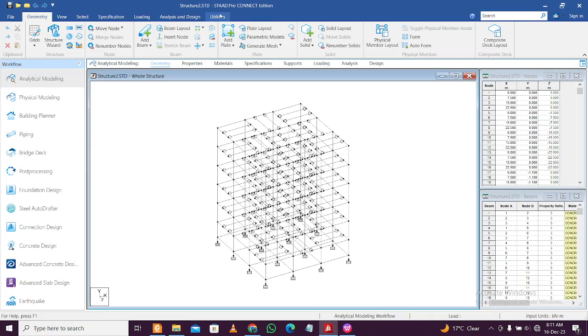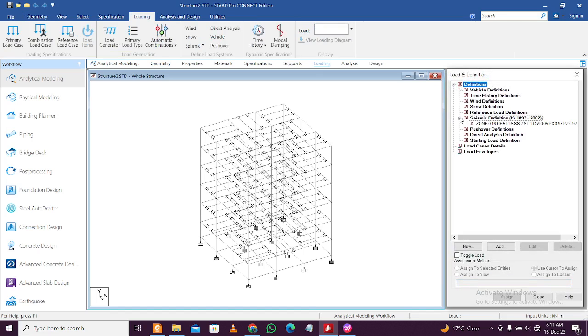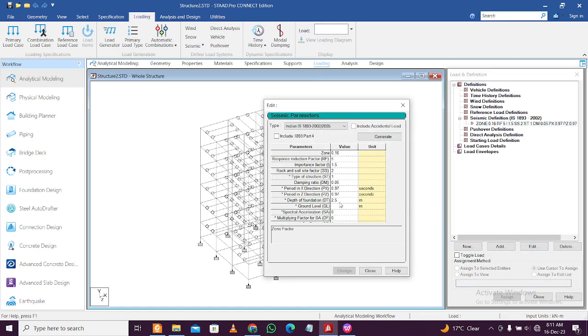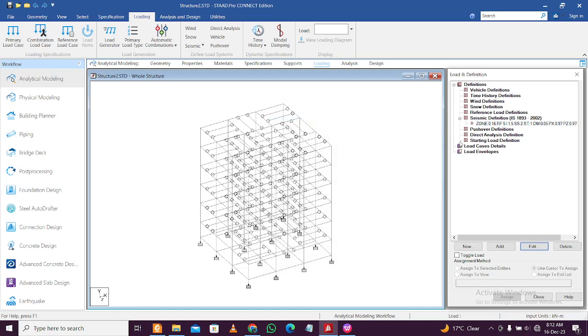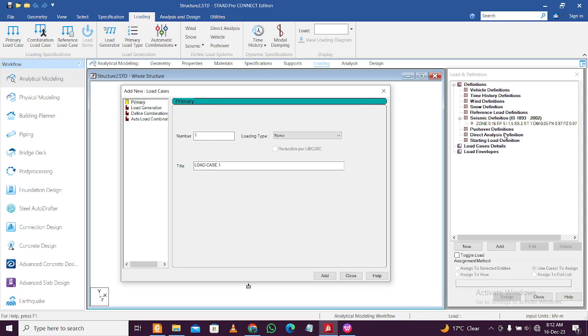Actually another thing you can change, but we'll change it later. So this thing you have to make sure you do. Now you can see this is okay here, driver structure 1. Now this is okay, this thing you can check. Now go to load case details and add the loads here, and the remaining seismic weight we'll do afterwards in the STAAD editor itself, so that we don't have to do much work.